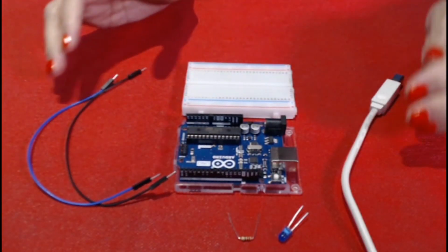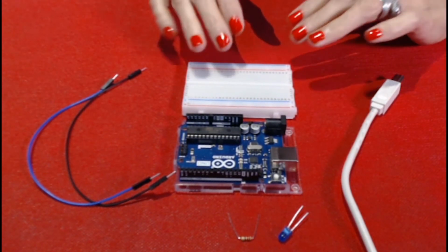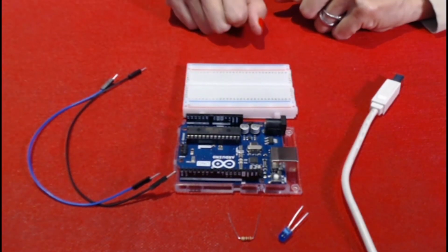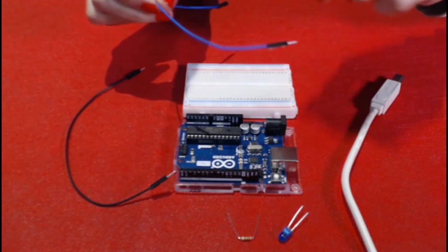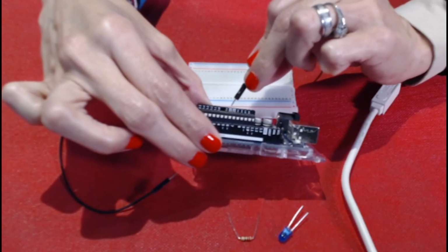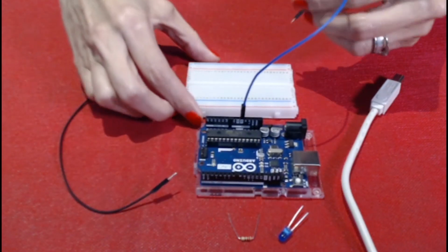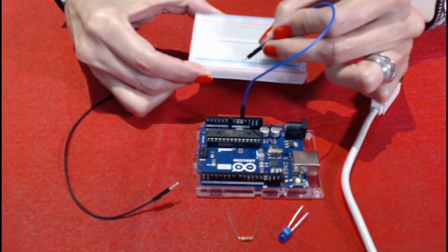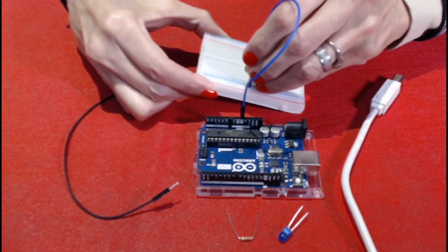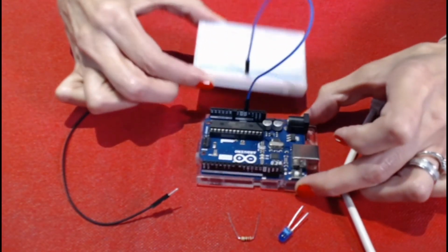So our next step is going to be the engineering prototyping. We are going to follow the instructions built in Tinkercad to start to design the wiring. The first thing here is going to be the connection of the ground. We are going to take one cable and look for the ground, which is in one of these sections of the microcontroller. We are going to connect the pin, and this one is going to be connected to the blue section of our breadboard. So we connect the pin like this, and that way we have the first connection.